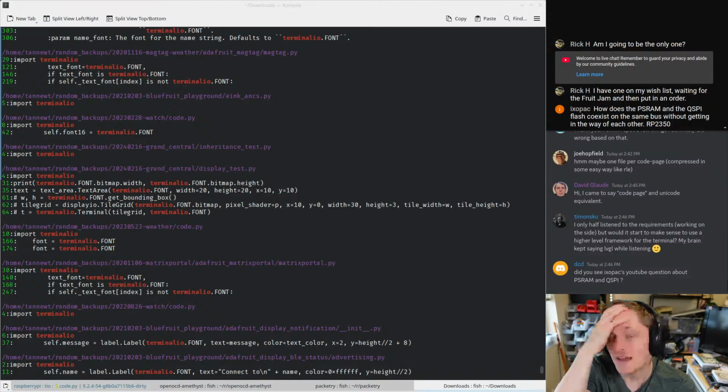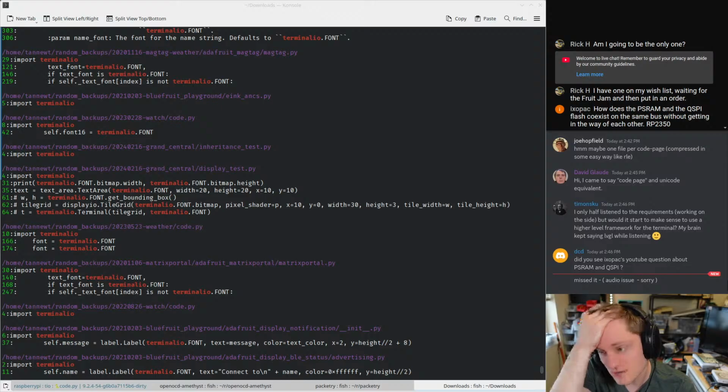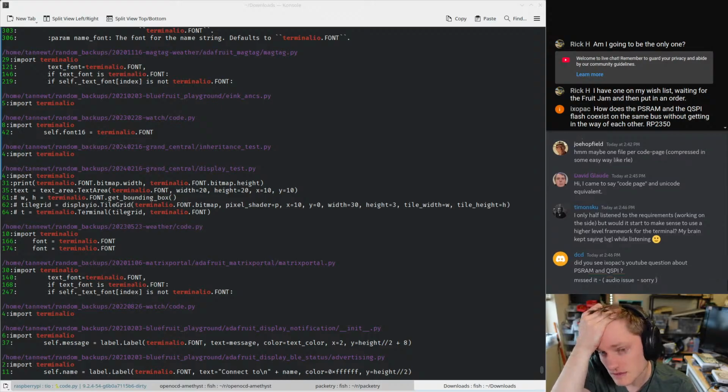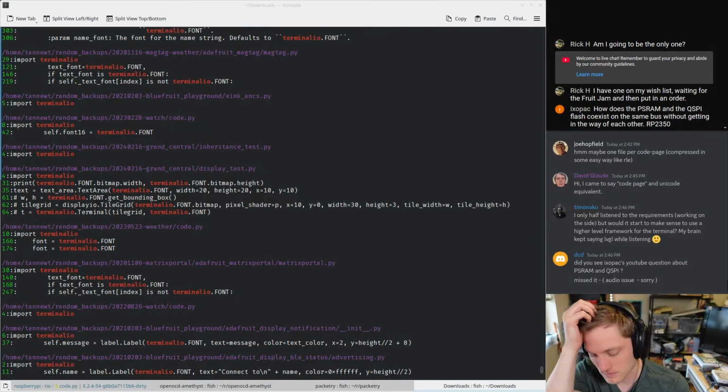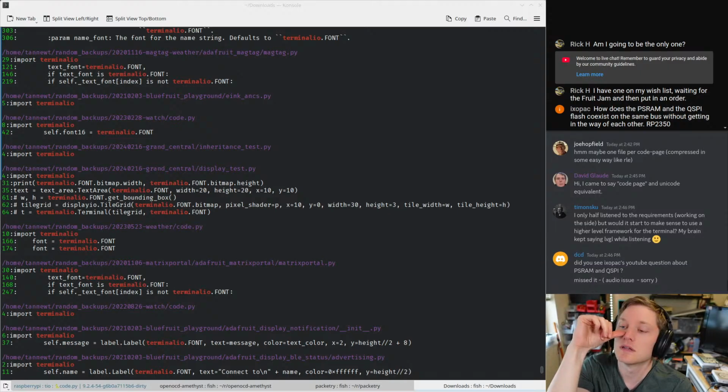I really think moving glyph storage out of the firmware into flash would be really cool. That would reduce our file sizes a lot for anything that has it built in. What I was thinking is we should only include the characters we need to render a URL on the screen for like a help message.